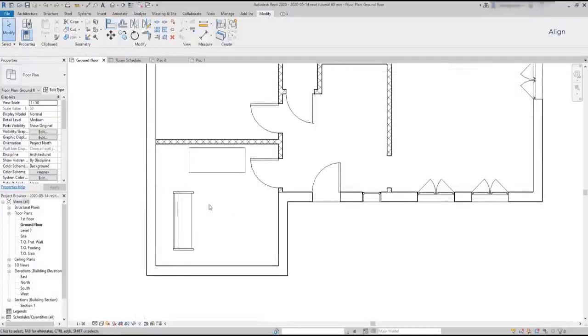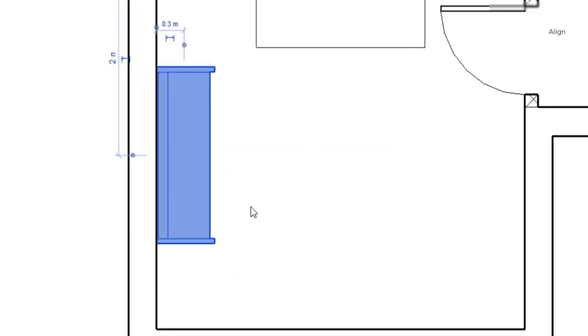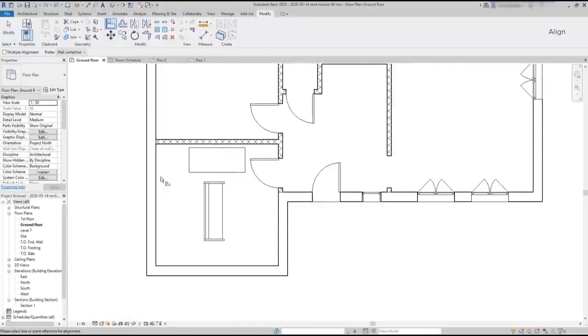Second example. Align this furniture element towards the wall. It's a nice sofa. Oh, and it's interesting to know that I can also move elements by clicking and dragging them and placing them where I want. If I try to put the sofa against the wall, I can't do it with 100% precision. With the Align tool, I do the same process as before, but this selection line is not the one I want, because the sofa would go inside the wall to match the center line.